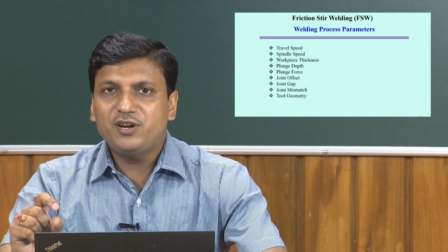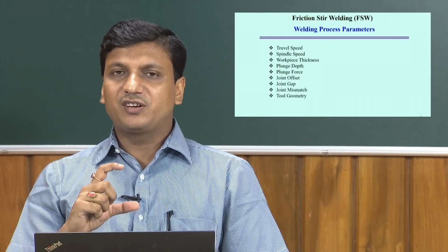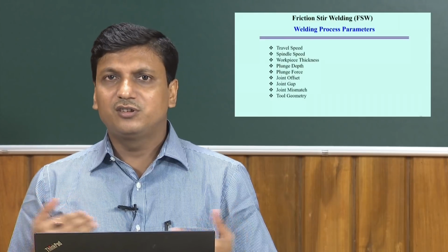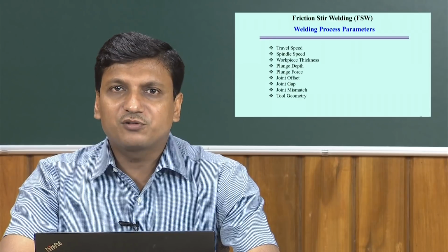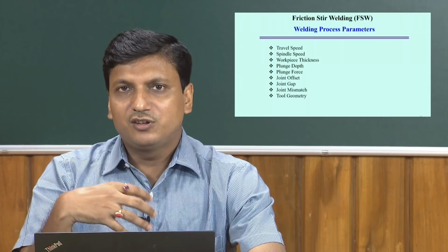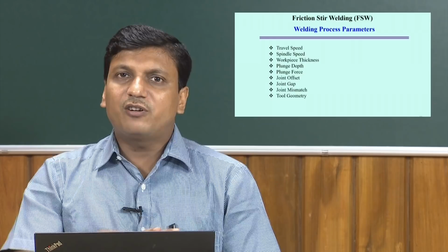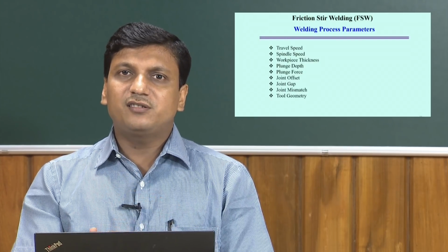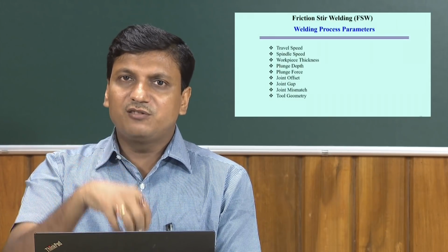Depth means using the pin, up to what extent we can give the depth of the tool. That means plunge depth is more or less equal to the height of the tool pin. Then plunge force: during plunging there is some force necessary to keep the shoulder in contact with the workpiece surface, to hold the workpiece surface and to make constant material movement also. There is some axial load required from the tool.